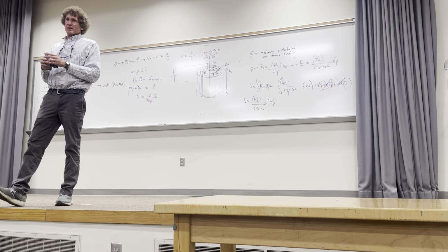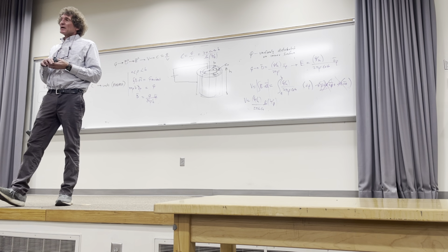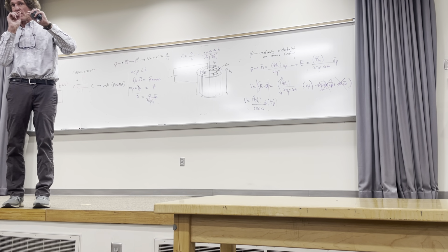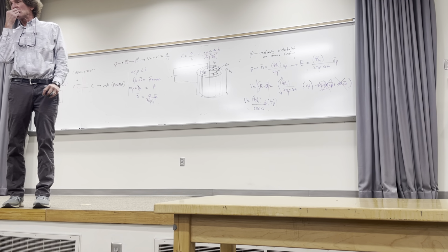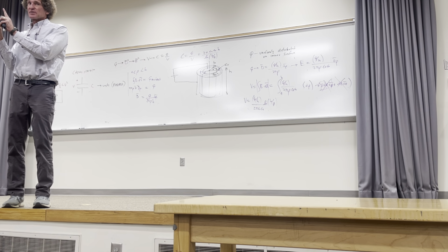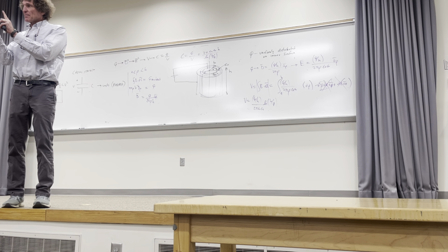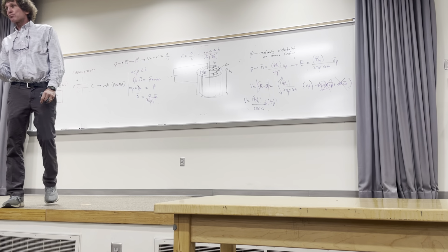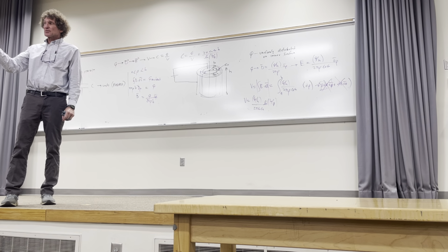Now, you think that seems like a lot. Well, yes and no. Because we will learn that when you get filaments of conductors, you all see thin wire copper, right? Filaments of conductors get something where you get field enhancement on the tip. So even though the difference between 2 points may be 1,000 volts, the field enhancement of that tip may cause an electric field value to be something of about 300 to 400 times what it would be just by taking the voltage difference divided by the distance. Could be a lot more than that. So you can get breakdown initiated by that, and as soon as it starts, it's almost impossible to stop if there's enough charge behind the system.